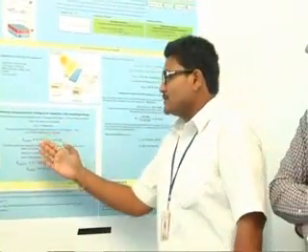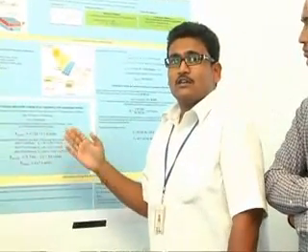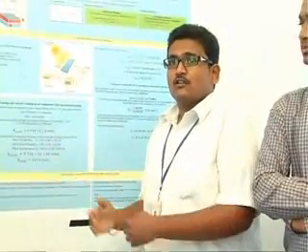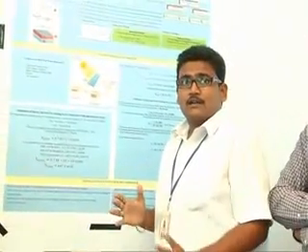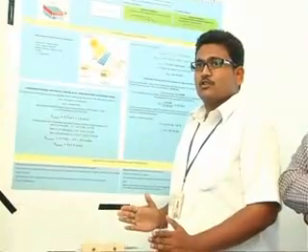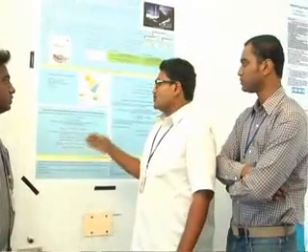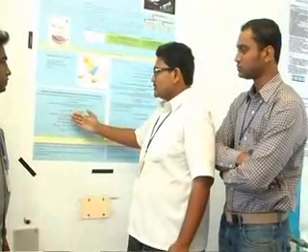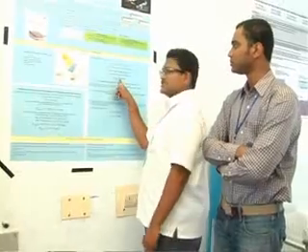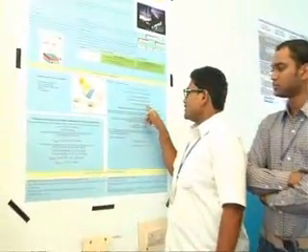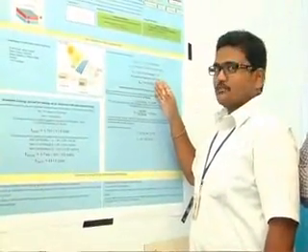746 watts of energy is not enough to run a 1 HP motor, because there is no manufacturing company which can produce a 100% efficient 1 HP motor. The efficiency is around 60 to 70%, so we need to take 1.2 kilowatts of energy. For 1.2 kilowatts of energy, using conventional energy, we will be charged around rupees 34,342 per year, which is approximately 35,000.